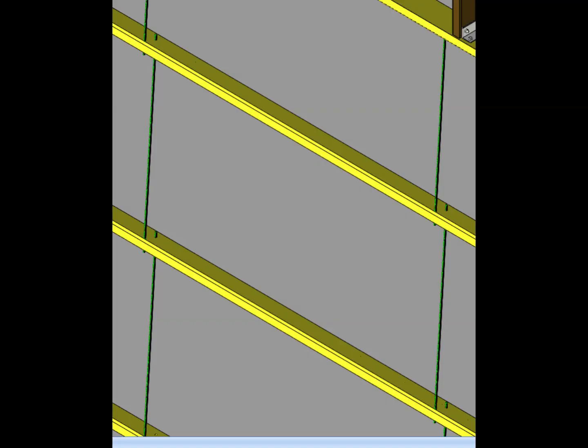Another important point is that the exact configuration of sag rods can vary from project to project. Therefore, we should not assume that every PEB will have exactly the same sag rod arrangement. The correct location, spacing, connection arrangement, and quantity should always be taken from the project-specific structural drawings and detailing requirements. In this particular model, we are using the actual project arrangement to understand the concept.